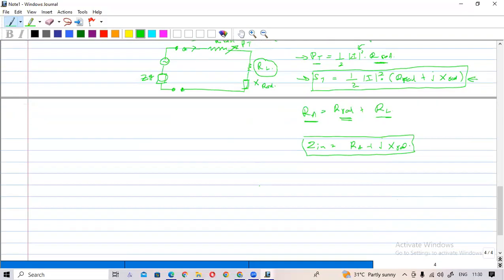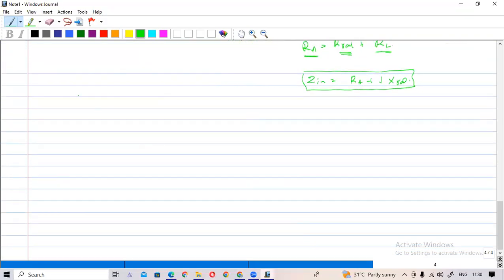Okay, so this equation, most probably: P_R over P_in, the transmitted power and the received power, is equal to (lambda over 4 pi R) squared. R is the separation of the two antennas, lambda is the wavelength. Then the transmitting antenna gain, the receiving antenna gain, and efficiency may also be there.